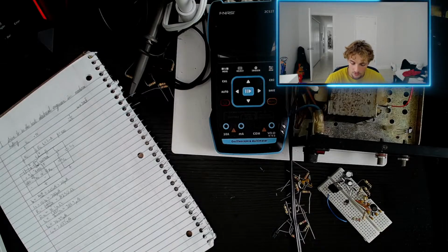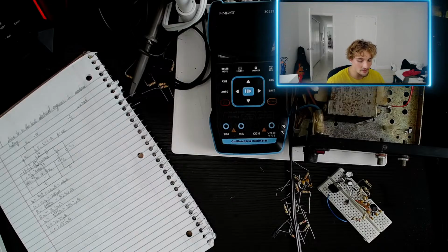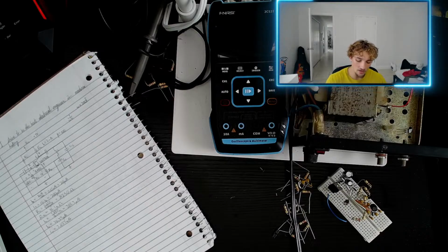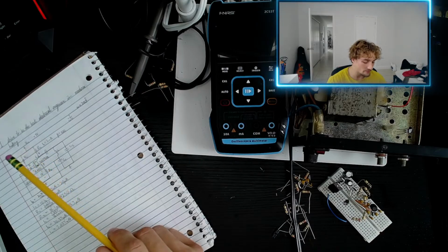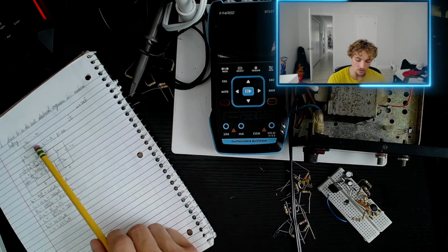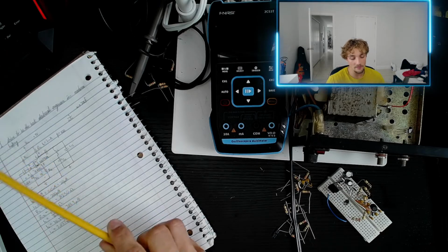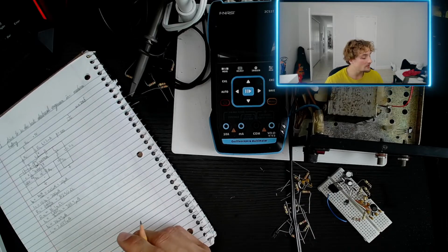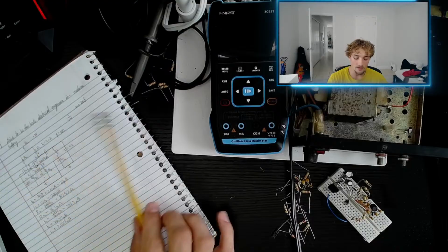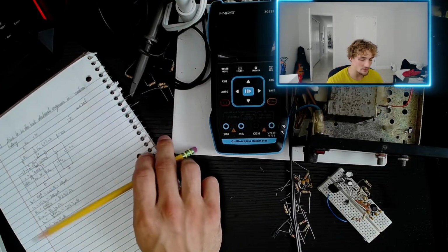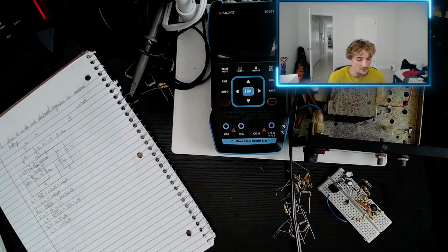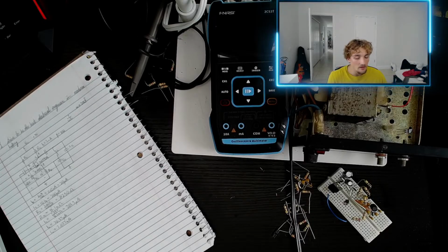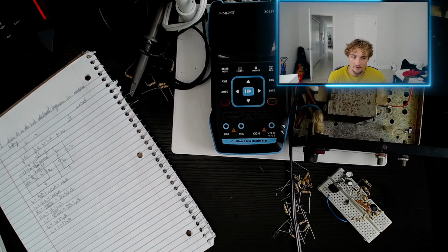So now with this current, we're going to have another assumption: we want half of our supply voltage across the collector resistor, because we want to allow maximum swing, right? We don't want any distortion of the output signal. That depends on our output voltage. If we have a supply of 9 volts, then half of that is 4.5 volts. That means we can have a maximum swing of, what, would we have that again?